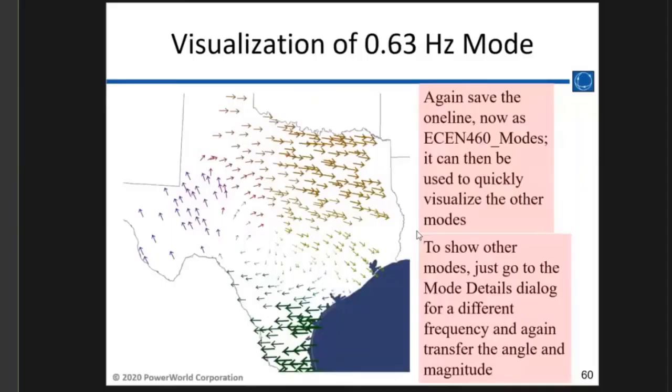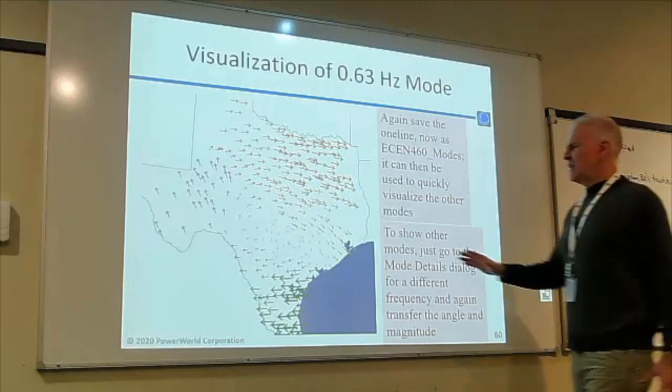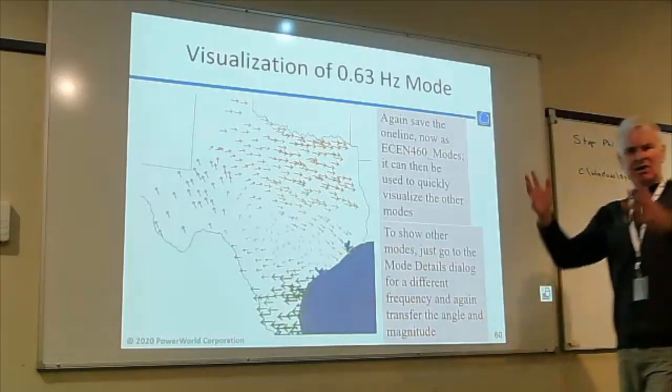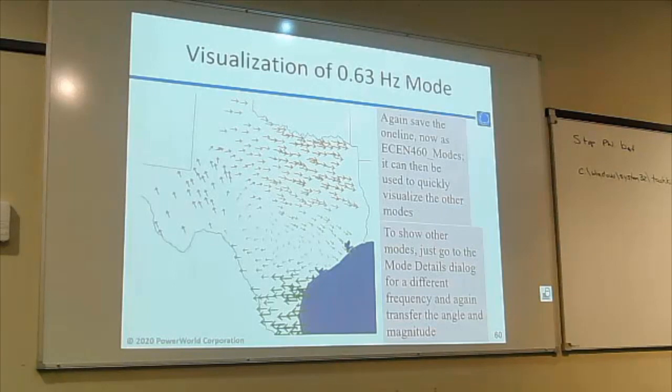We have a WECC equivalent, not equivalent, synthetic grid that we built using a 765 kV transmission system, and that one in the west also has this oscillation spinning around to it. We can do this, of course, with real systems too, and we've looked at the different modes in the WECC, and we can easily visualize those modes. All of this was based upon data that we got from a simulation, but it was ultimately driven by the data. Once you run the simulation, you have the data, there's no model that goes into this. It's just driven by the raw data.